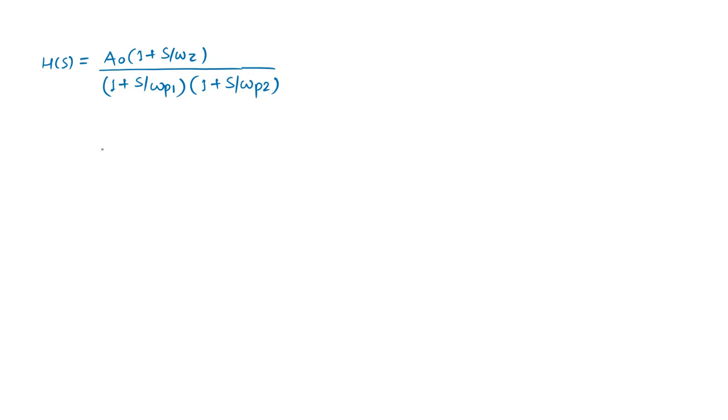So what we ideally considered, we have seen the single stage op amp was nothing but a first order system. Initially we have seen the single stage op amp, which is a GM cell with capacitive load. Single stage op amp is an ideal integrator. Okay, so it is an ideal integrator.